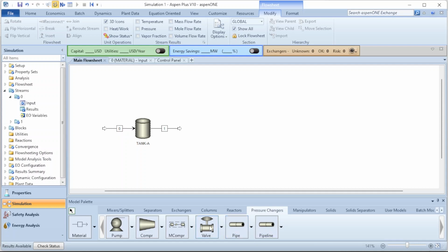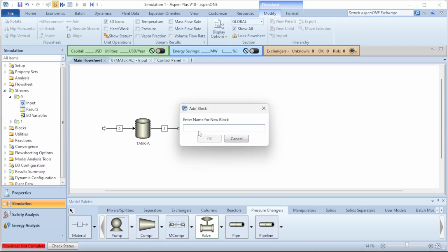Okay. So now we have to put the valve to the flow sheet. So just select the valve. If you don't like this icon, you can click down, you find different ones that you like, then you pick. So I will check in this one and come to the flow sheet and select it anywhere. So now I'm supposed to give a name to it, and now I'm going to give it v-1. Okay, it was valve 1, so valve-1.